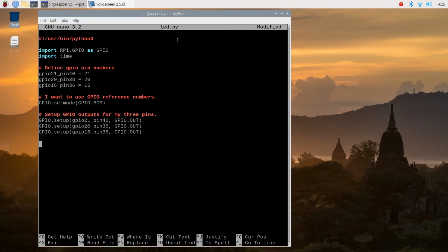And before we actually do anything with the pins, let me do a little print statement. We'll say, start of GPIO program. Okay, there we go. Now I want to flash the LED 20 times, so I want to repeat 20 times. To do this, we need to define a variable. So we're going to say for loop in range 20,